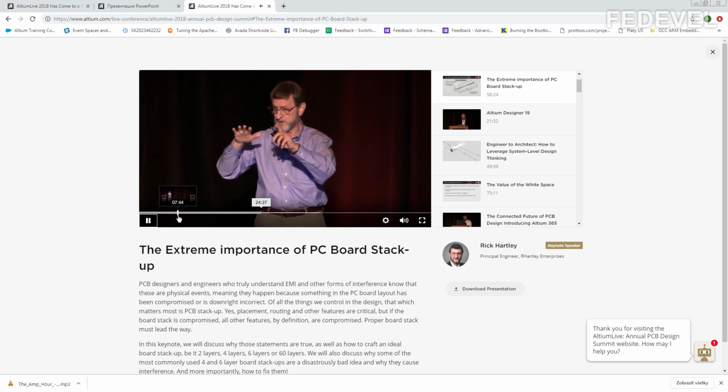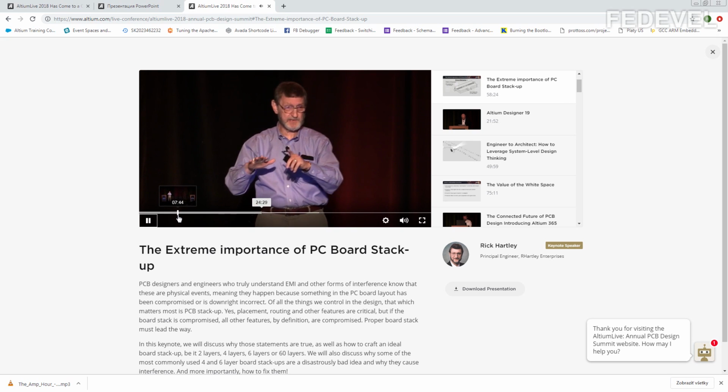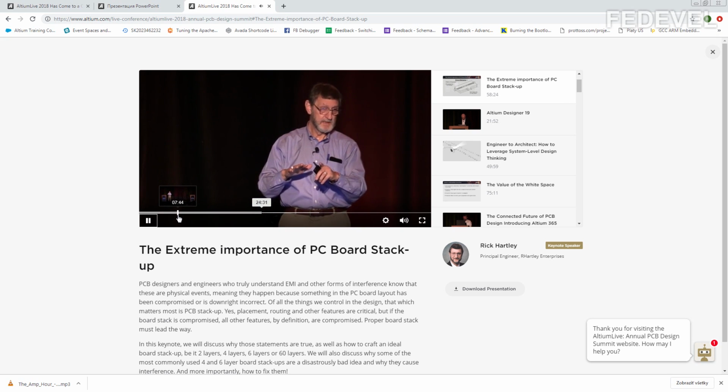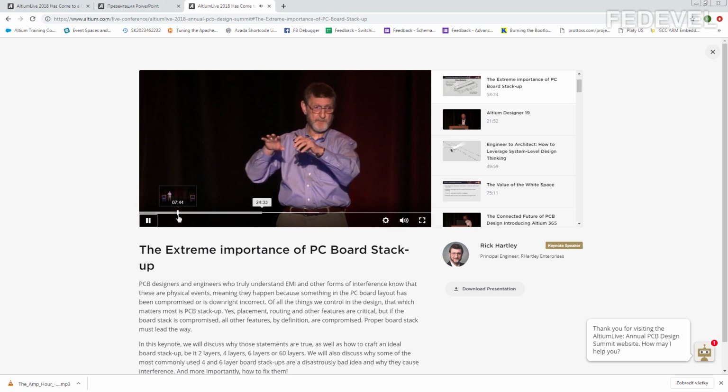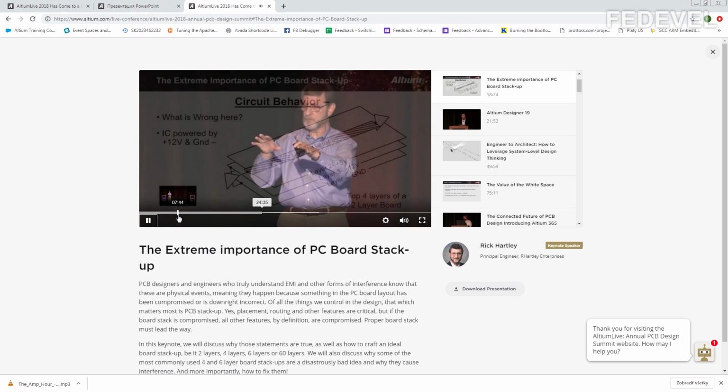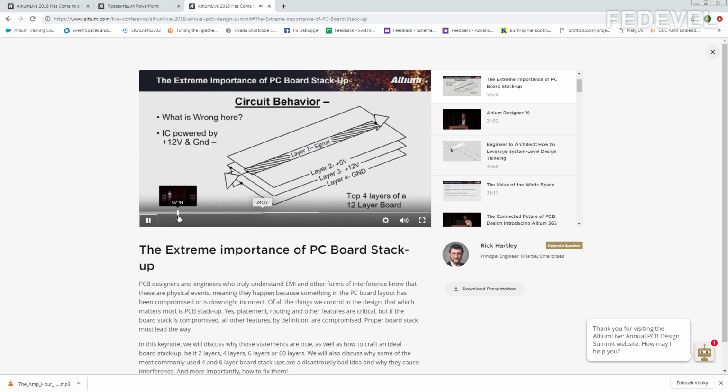So the energy is not going to just couple through the copper unless it's super low frequency. What's going to happen is it's going to spread out, couple through the holes in the copper and around the edge of the copper, down to the dielectric space between 2 and 3, and then create a current in the 12-volt plane to get back into the driver.